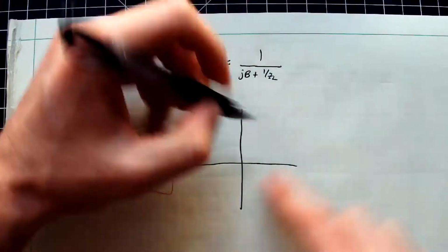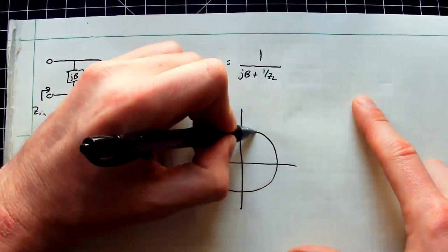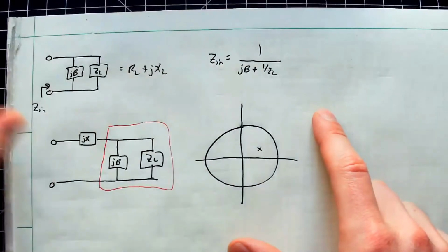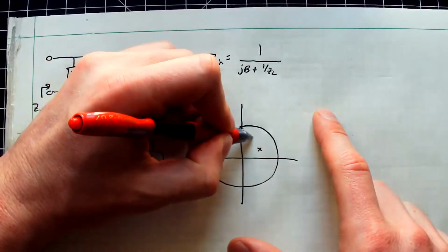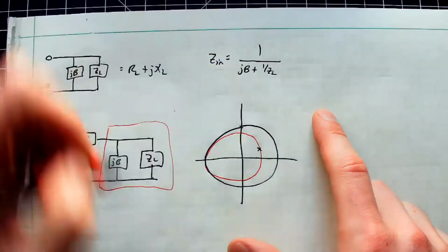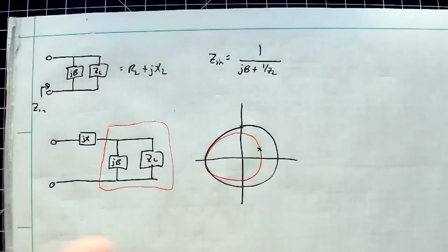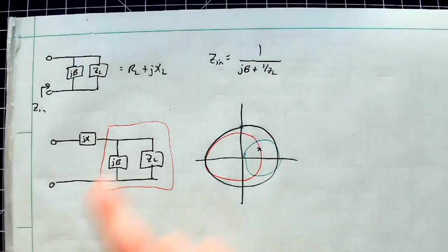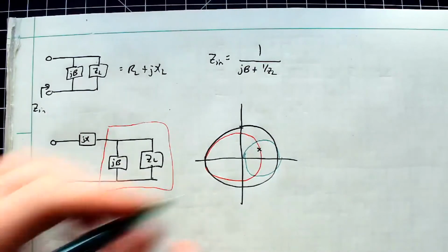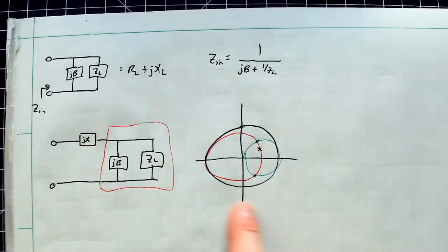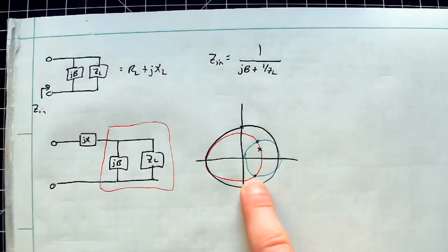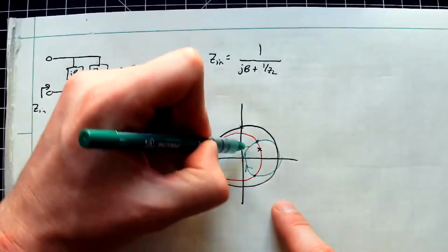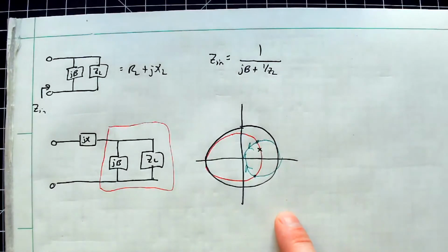So if we draw a quick Smith chart here. By adjusting this knob here, I had some starting points and it took me along these arcs over here. And then I had the magic circle over here, like so. So I adjust this knob first. I can go up or down. It will either take me to this intersection point or that intersection point. And then as we just found out, once I'm on this circle, all I need is an equivalent series, which will then take me either that direction or that direction.